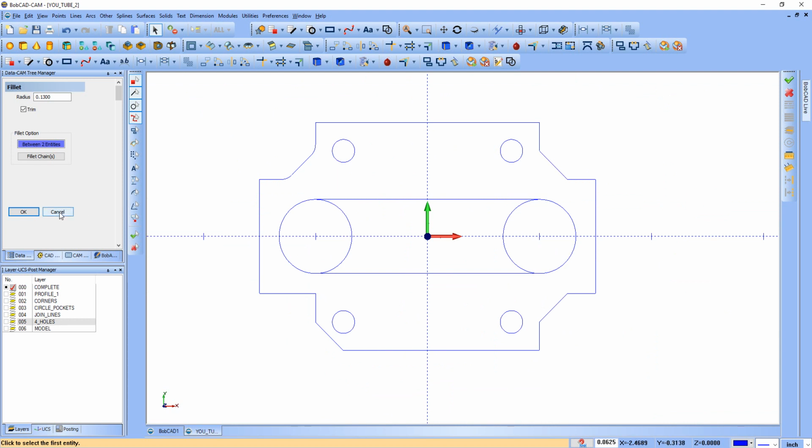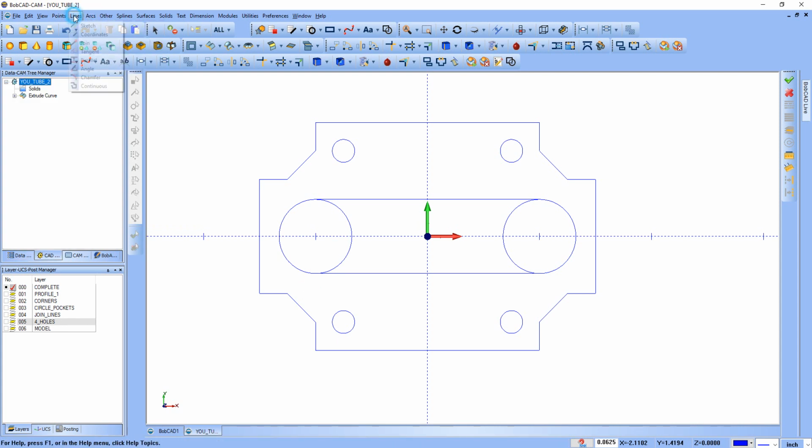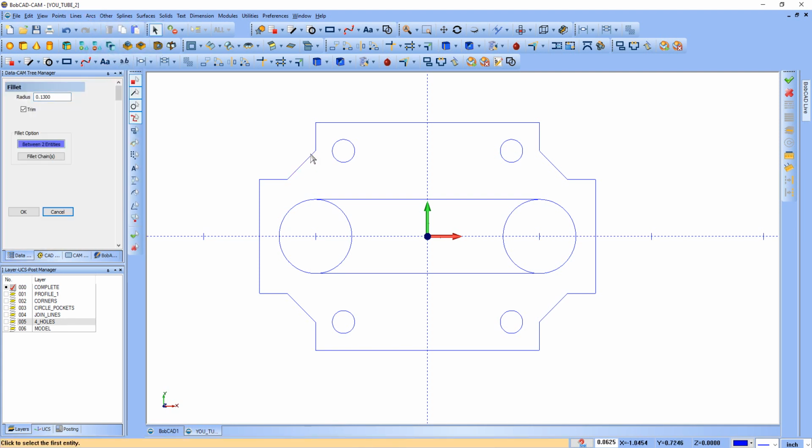You know what? I chamfered the wrong corner back there. Let me hop back in here and chamfer the right area. So now again, the chamfer was in lines, and then chamfer, and then arc, fillet. That's going to give you that radius we're talking about. So I'm going to go through and hit these. And again, I'm basically just redrawing everything I had, and when I'm done with this, it'll match the model again. And then I can hit on some tool paths.